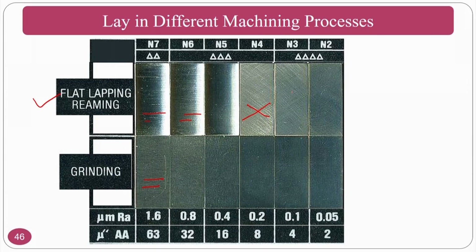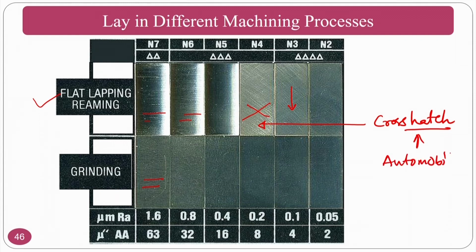If you measure on this surface like a line, you will get a digital value, but sometimes people will specify the lay, like cross hatch pattern. This is cross hatch pattern. Normally this is required for your automobile engine cylinders. Okay. Why do you require it? Because your lubrication and other things will be taken care of, and the lubricant will stay in these cross hatch patterns and give smooth piston movement, and for that purpose normally people do the honing process.